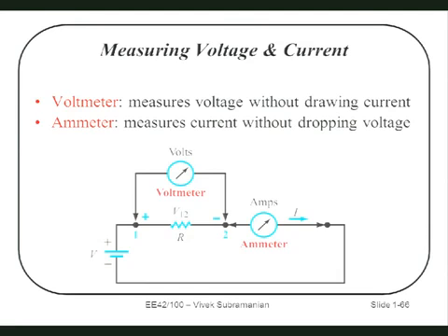And then it uses Ohm's law, which we're going to learn about in a minute, to calculate. Because the resistance is related to the current and voltage in direct proportion. So, put a known current through, measure the voltage, that's a measure of resistance. That's the way modern multimeters work. Early multimeters actually would put a known voltage and measure the current, but that's an inverse function, which is not so easy to calculate. So you gave the right answer. Okay. So that's how we measure resistance.